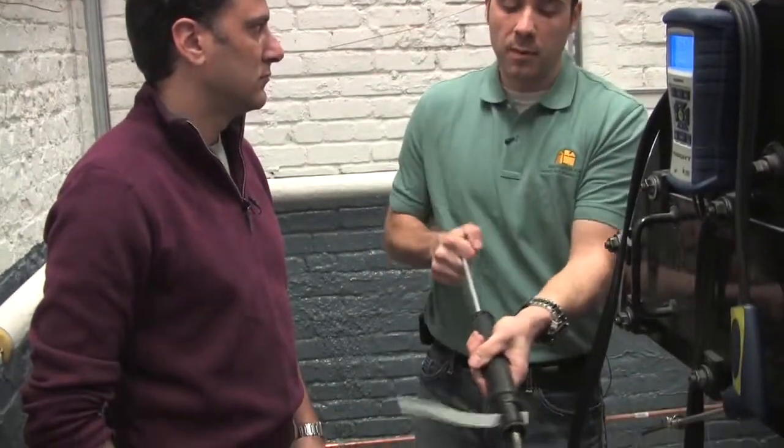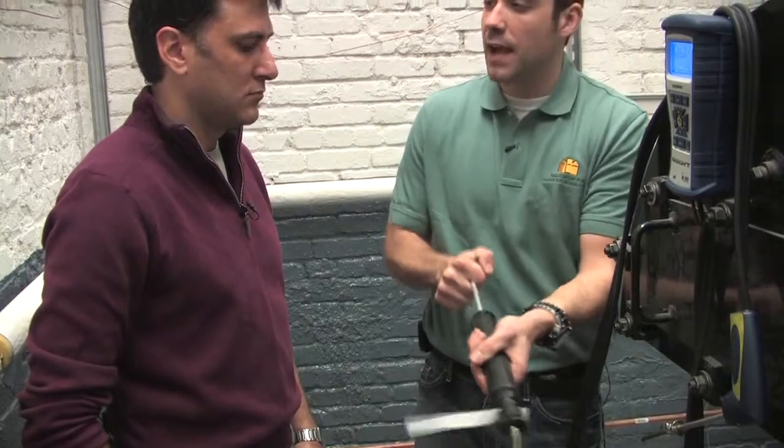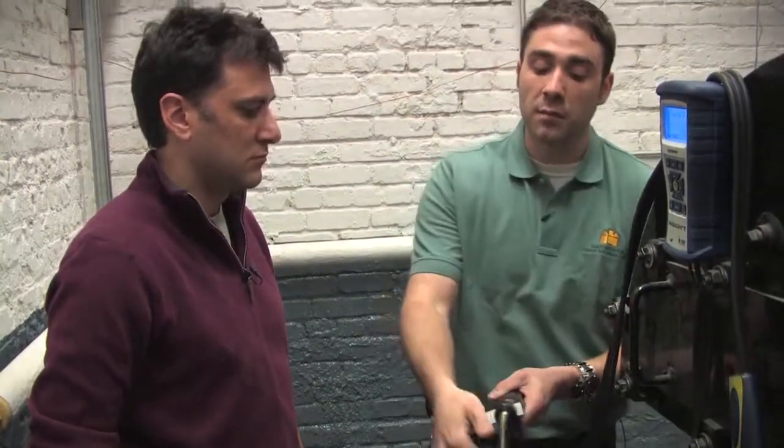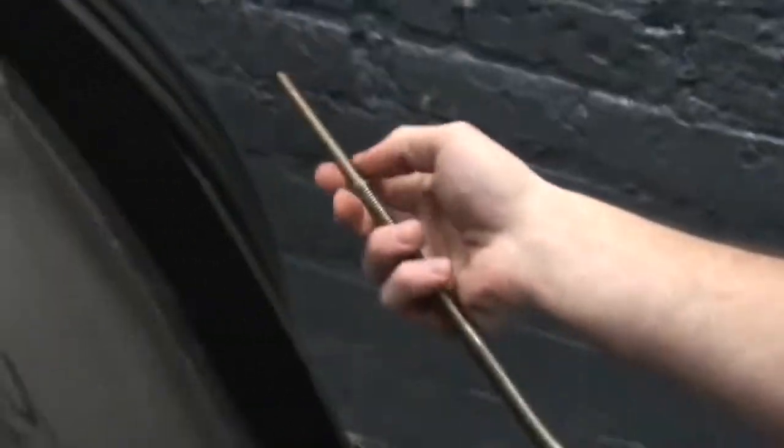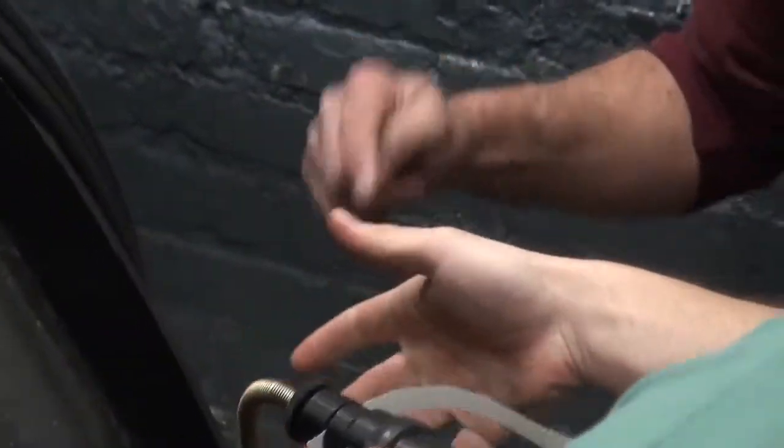So bring it inside, let it sit for a half hour. Most boiler rooms are very warm, so it'll come up to temperature pretty quick. So that's one thing I would recommend. The next thing is just to give it a few pumps just before you start. Pump it maybe 2, 3, 4 times just to clear out any dirt or debris that was in the nozzle prior. I mean, if you did a really sooty test before, there may be some debris left over and you don't want to compromise the reading.